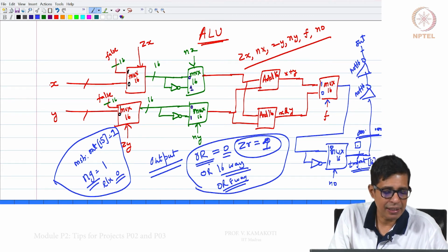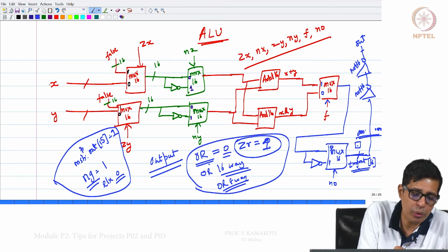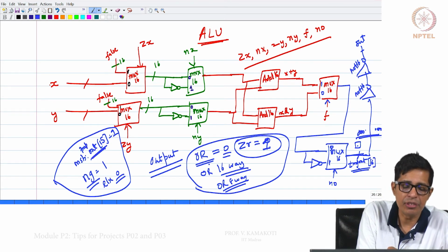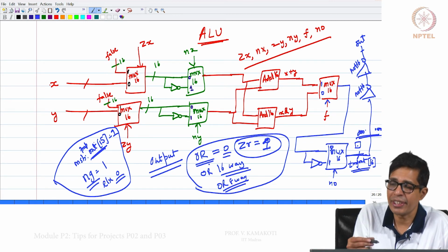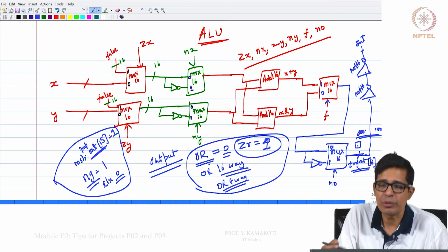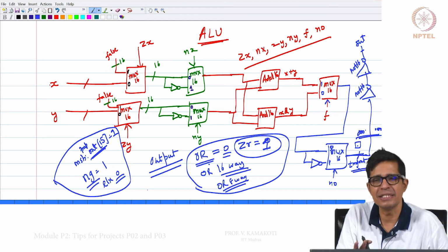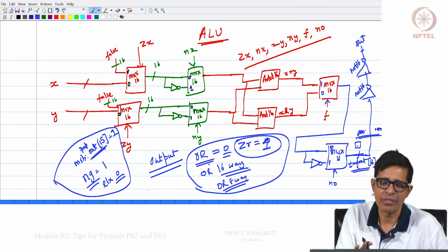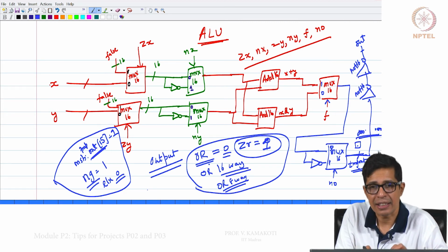And secondly, I can't take a part select of an internal variable. So, I can't even get this temp out of 15, which if it is 1 then NG is 1. So, I can't get temp out of 15. So, essentially I have to generate 2 other modules or chips to basically handle this. So, there will be a small challenge here, I will leave it as an exercise for the reader to basically get your NG and ZR correctly tested.